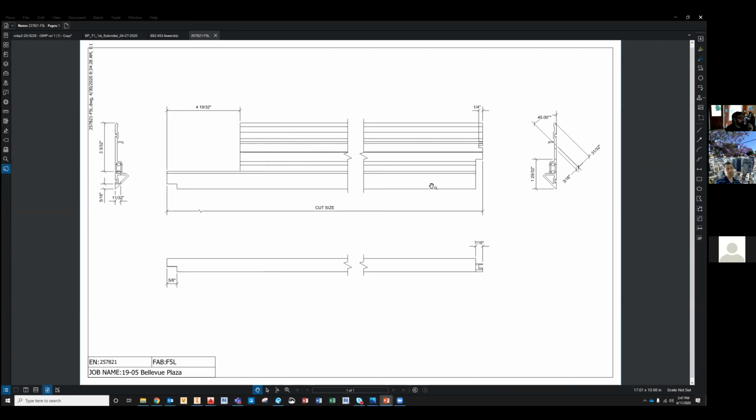And if you have a part that's too long, say you've got these break lines here, if we wanted to have a dimension here, the Inventor DWG is smart enough that you can put your dim line on this point and on this point, and it'll give you the dimension of the actual part, because it already knows what the length of the part is. If you throw the break lines in, it accommodates for that.